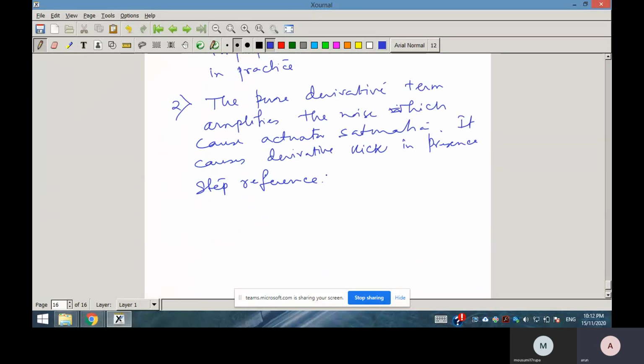What is derivative kick? Suppose you are applying a step reference signal, and initially the output is 0. When that step reference signal passes through the derivative part, since the PID controller parts are in cascade, it will become an impulse. So a sudden kick will happen. A suddenly high magnitude control signal will result. That is derivative kick, which is unavoidable.